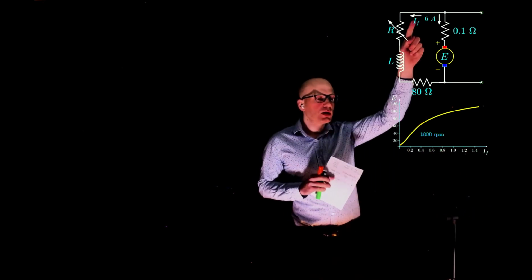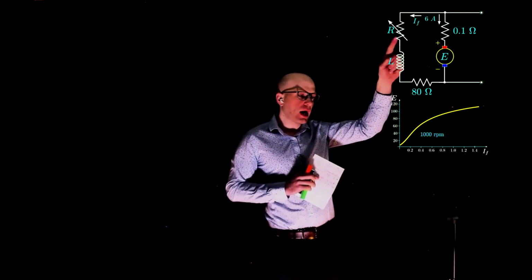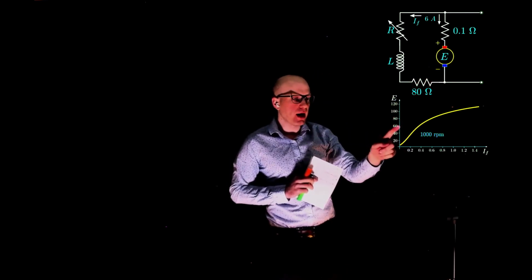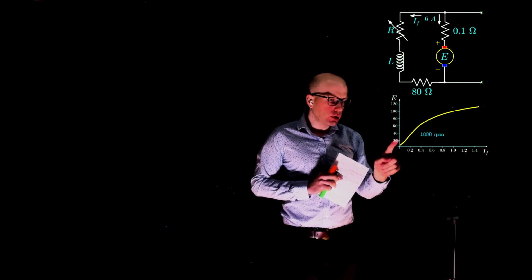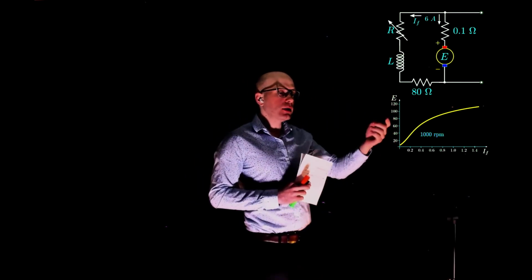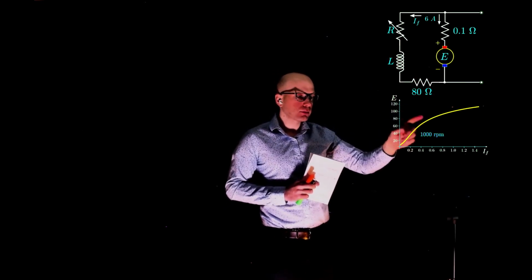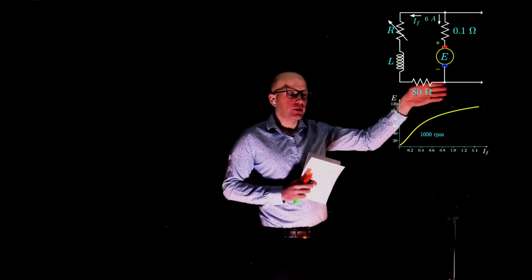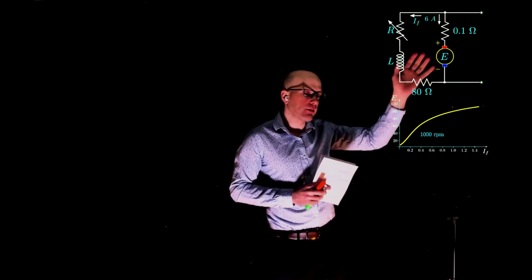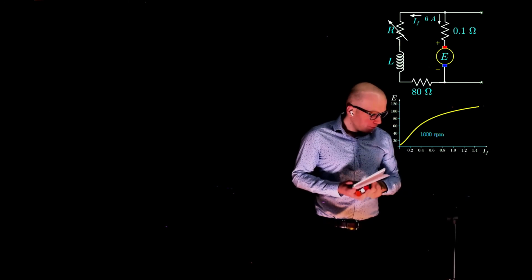Because you see, this is the current through the electromagnet. By changing R, we change this current. And given that this is rotating at 1000 RPM, then you're going to read a different voltage here. So R is a variable resistance that is a way to control this voltage read here at this constant speed. So by adjusting R, if the speed eventually changes, we can change R to keep always the same voltage being read at that specific point.